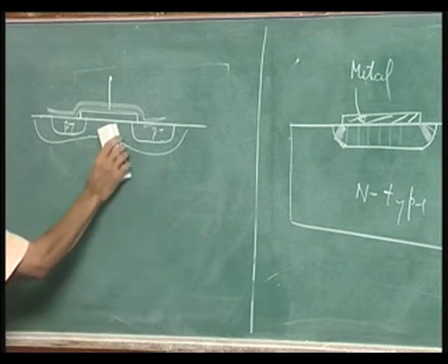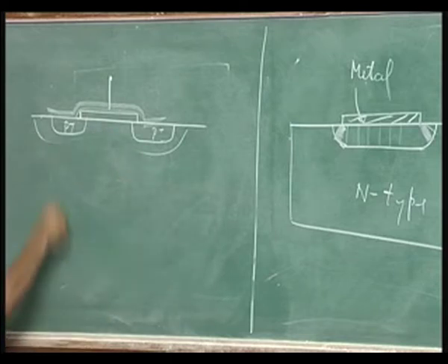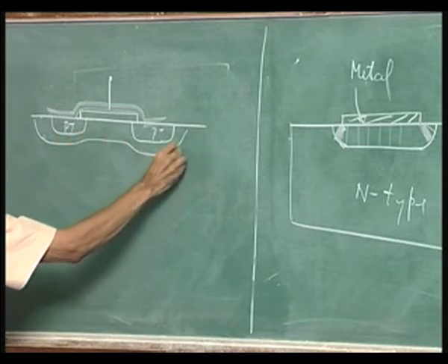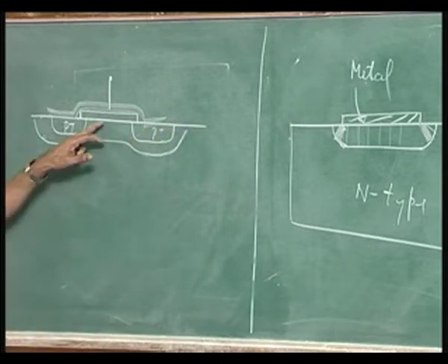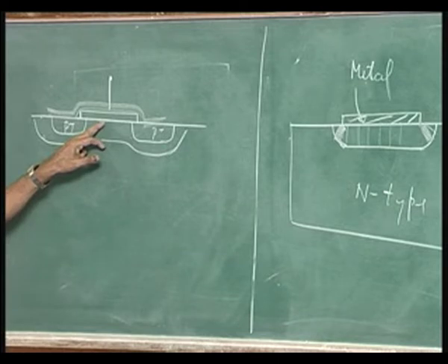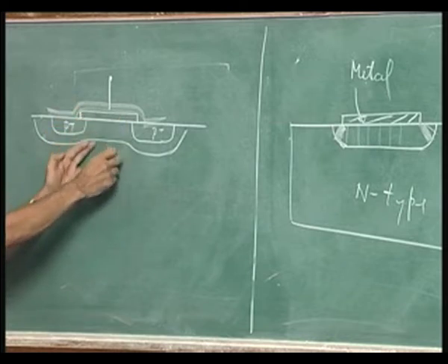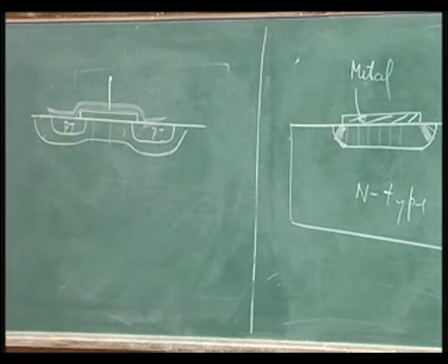Okay? The depletion layer actually spreads like that. As far as the Schottky barrier is concerned, it is plane parallel, there is no crowding, all the field lines are vertical. So, as far as the Schottky barrier is concerned, there is no change in the peak electric field, everywhere it is the same thing, governed by the one dimensional law.